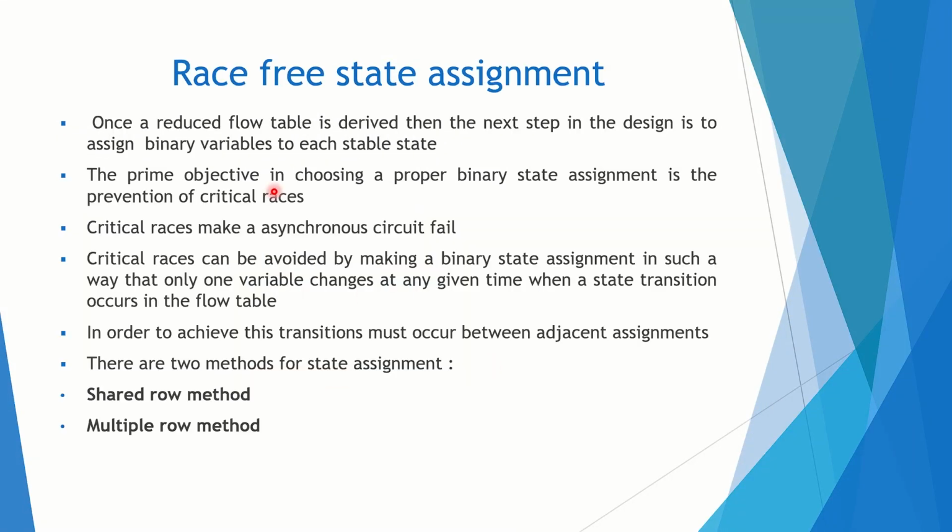Next we'll see race-free state assignment. In the last lecture we saw the races, that is critical races and non-critical races. Non-critical races are not a big issue, but we should not have critical races. Critical races make an asynchronous circuit fail.